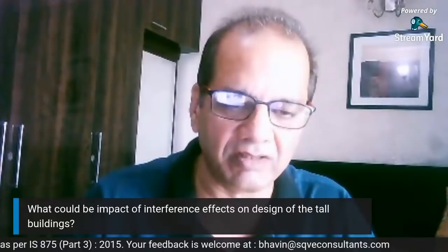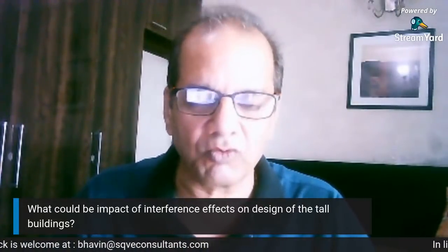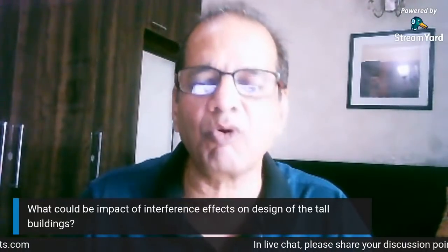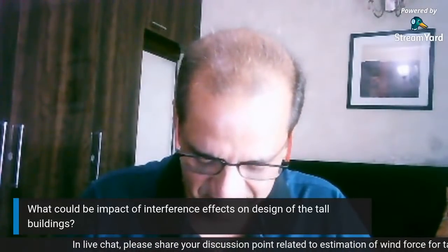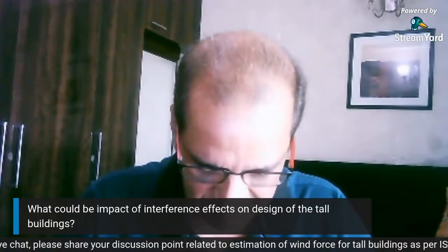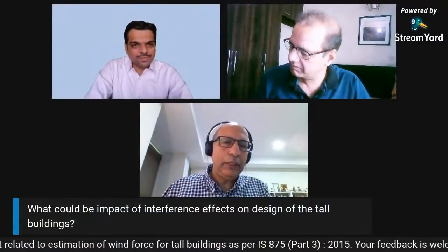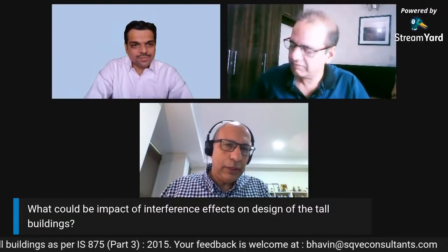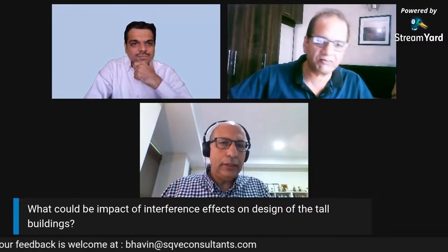It's a very typical thing because of the nature of the wake flow in between the two. There have been very rare cases where the upstream building is also affected, but this is due to a mechanism called the lock-in excitation mechanism, and it's only where the upstream building is in very close proximity to the downstream building.